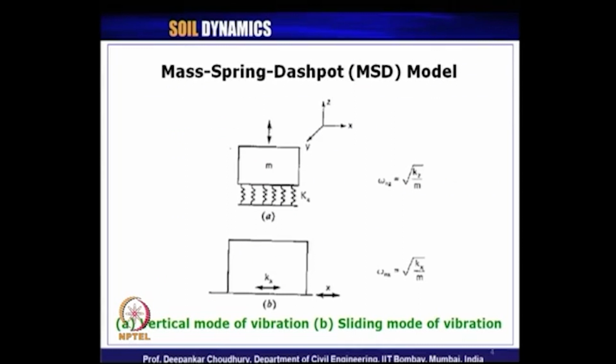And then we had started with our second method of analysis using mass spring dashpot model or MSD model. In that case, we discussed the expressions to compute the natural frequency of the machine plus foundation system for each individual mode of vibration, that is for vertical mode of vibration.